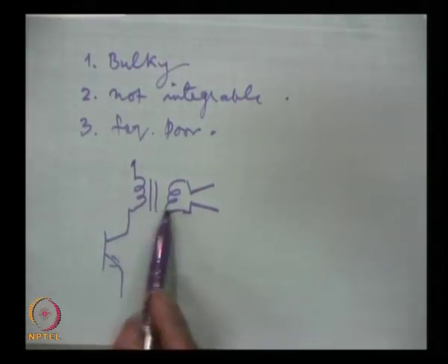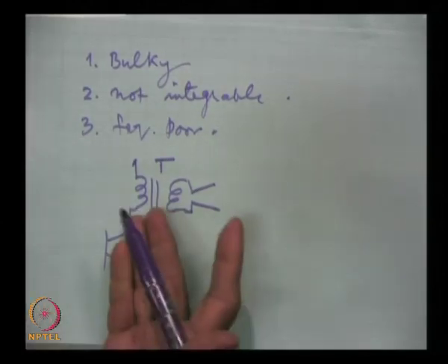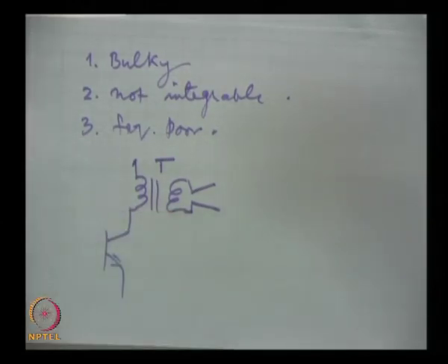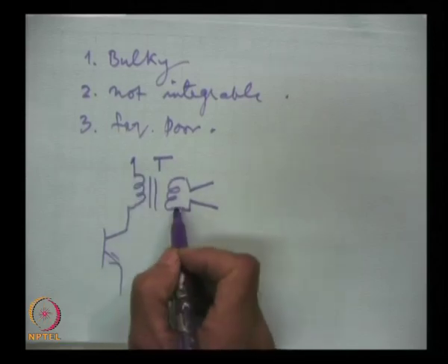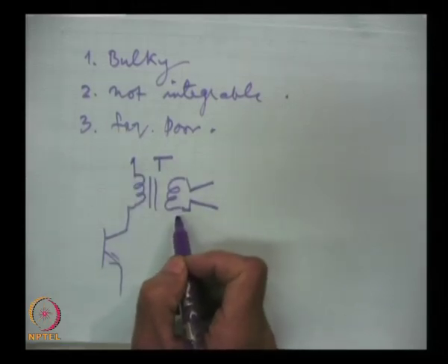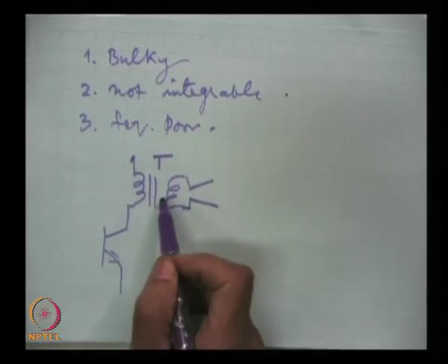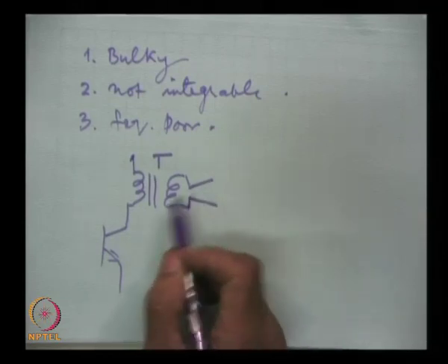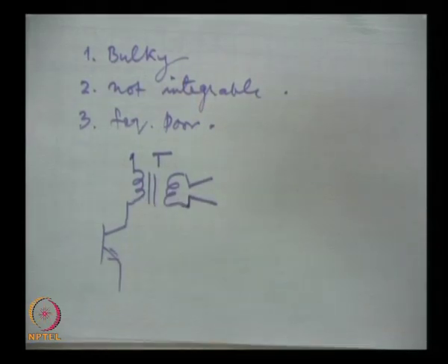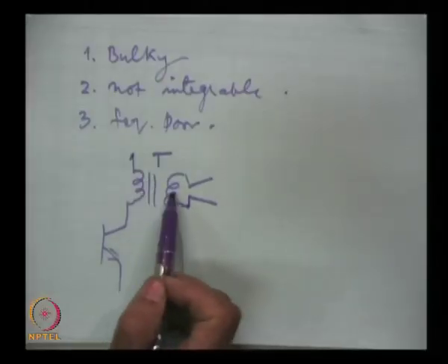This is transformer coupling, this is transformer and it is used if you open your radio sets, transistor sets, then the speaker you may find connected to a transformer. So, this is transformer coupling in which it can take large currents and hence large signals can be passed through the transformer, and DC will be blocked, no DC will propagate in the transformer.